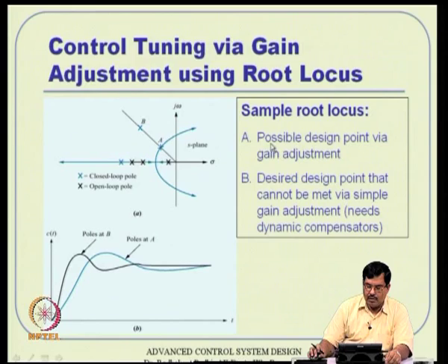So you can use those things and say, okay, if my system is largely like a second order system, then that should be my damping ratio, let's say. Then this will give you some angle, that is cos theta is that. So theta will be known. You draw a line, and wherever it intersects the root locus, you pick up that particular pole. That particular location on the root locus will correspond to a certain value of gain k. We know that each location corresponds to a particular value of gain, so I will select that particular value of gain.